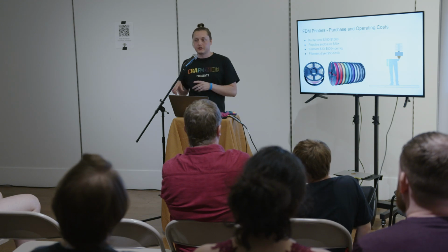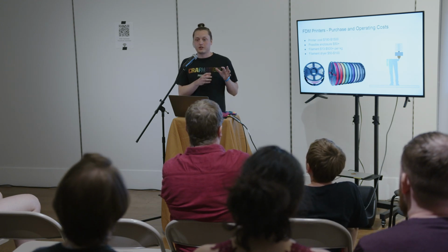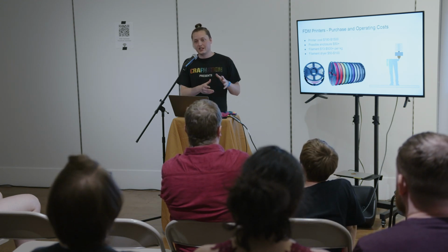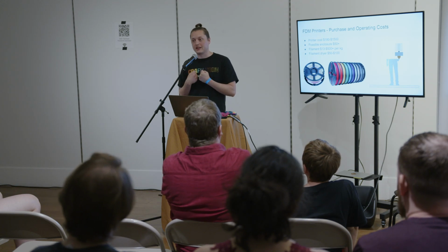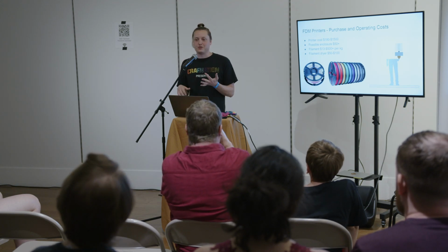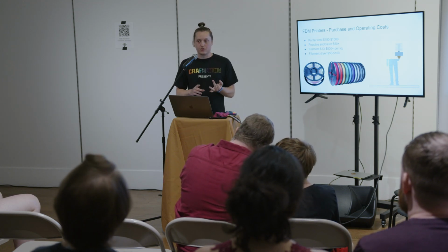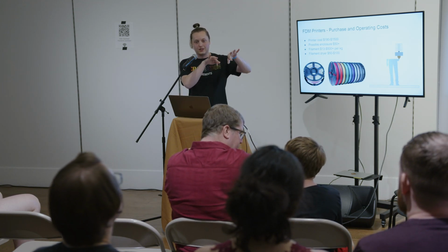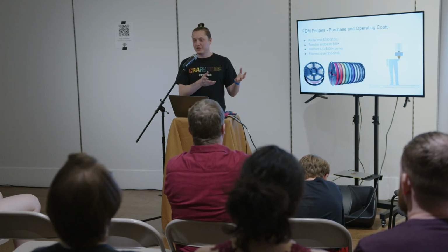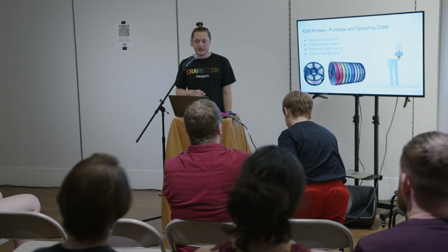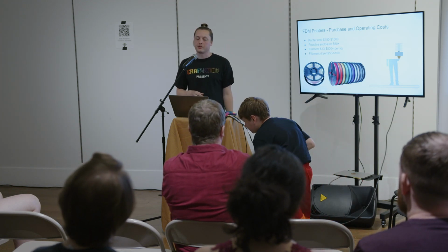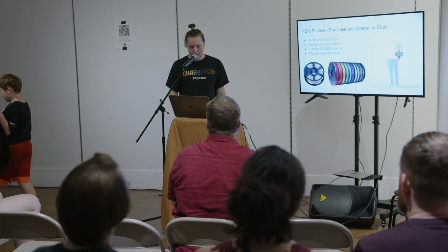And then if you live in really humid environments, some filaments are really temperamental with temperature and humidity, and they'll actually absorb water out of the air. Then they give you weird print things, like the filament will become really brittle and will just snap. Or you have lots more little stringy things on the print and lots of weird little stuff like that. So sometimes a filament dryer is required, but generally not super needed.